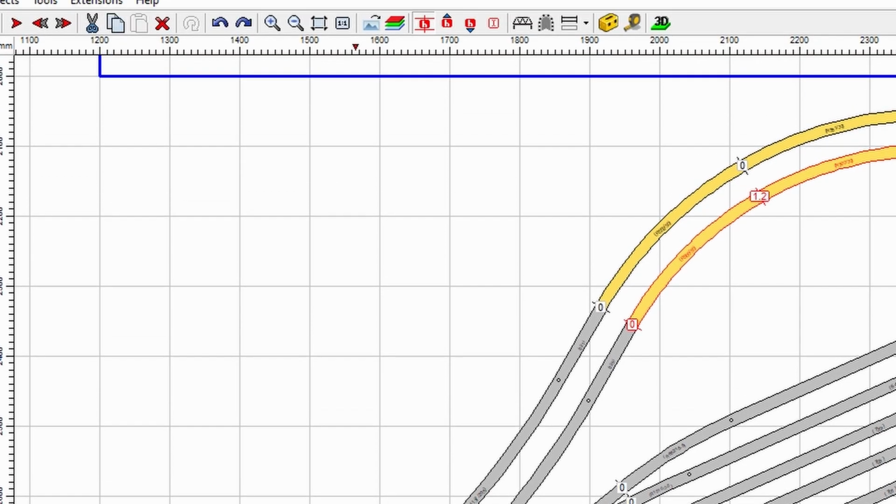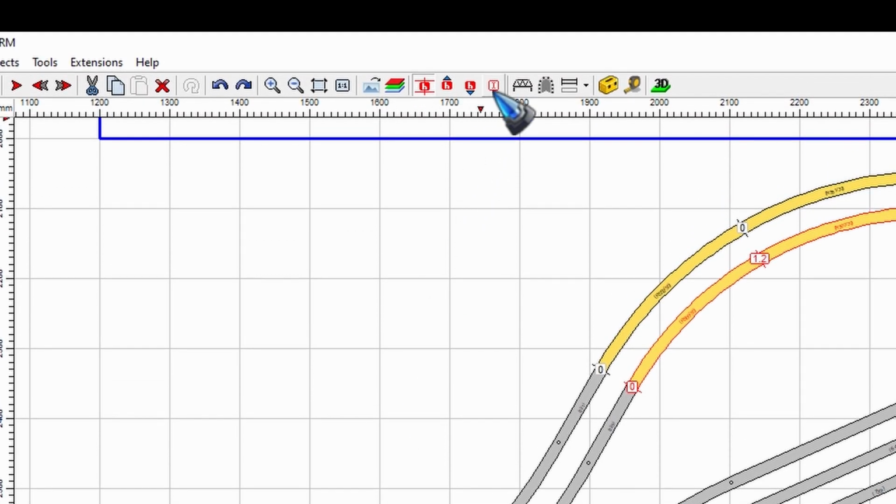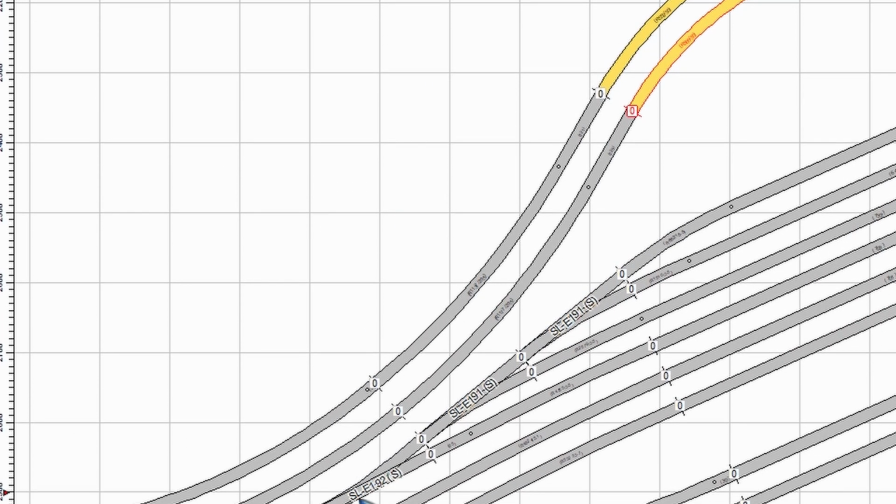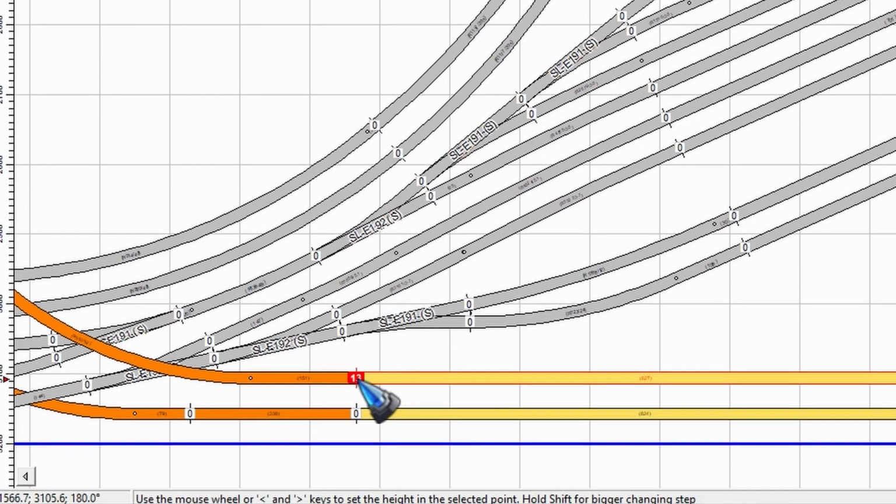Yes, there is. Here at the toolbar we see an icon called numeric height input. Let's click that, and that enables to just type in a number. I want to go to 90. It is right now at 13, so let me type 90 and look what happens. Yeah, that was not what we wanted. It just adds it to the 13 that already was there.